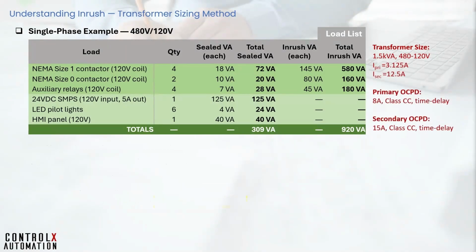Now that we have determined the overcurrent protection device sizing, we need to connect them using appropriately sized conductors. For that, we'll refer to NEC 310, which is a section of the United States National Electrical Code, NFPA 70, that governs conductors for general wiring, including their materials, insulation types, ampacity ratings, temperature limits, and installation conditions.